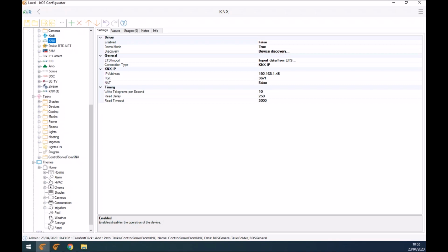One last question. This is a multi-floor, multi-TP line house. Assume that the BOS is connected to the main line. The filter tables will normally prevent local GAs from propagating to the main line. How do you handle all the traffic of group addresses, since all GAs now have to go to the BOS and the main line? Do you open up all couplers to all GAs, disregarding the filter tables?